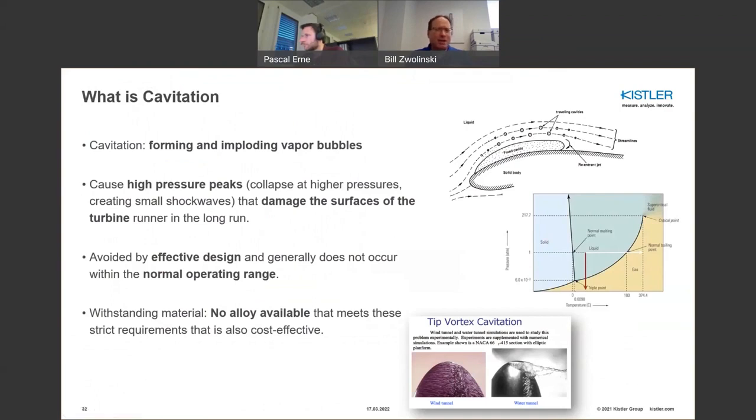So just getting into some applications, I just want to talk a little about cavitation. And cavitation, I guess, is the forming and imploding of vapor bubbles. You often see bubbly water with a propeller going through the water, and that can be a very visual indication of cavitation. What happens is these imploding bubbles produce fairly high frequency and high pressure peaks, and they could be very harsh on materials over time. So detecting cavitation gives you the ability to make some assessments as to, say, the integrity of various rotating equipment, for example.